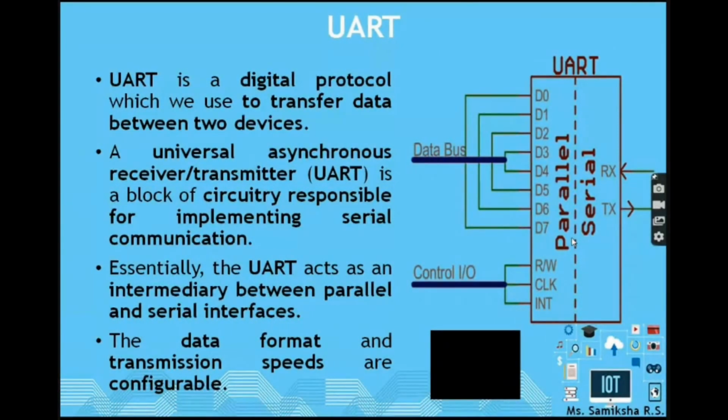UART will always help us achieve the communication because it acts like an intermediary between the parallel and the serial interfaces. And using UART, you can always adjust the data formats, that is, in which language these two devices should communicate with each other. That data format should be recognizable and understandable on both these different devices, parallel as well as serial. So you can always decide that.